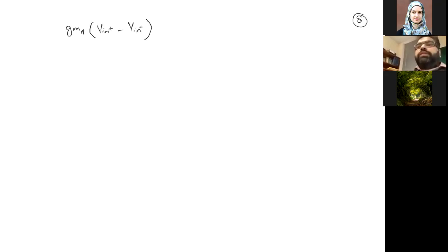If we replace in this expression, we are going to be left with something. I'll just do the small math and you can make sure to get your hands dirty yourself. So GMN times V in plus minus V in negative plus VGS minus V out divided by RON plus 2 times VGS3 times GMP equals 0.